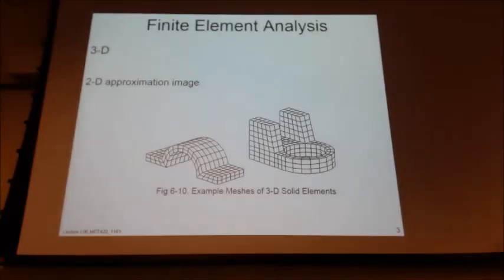And again, like in 2D, the tetrahedron wasn't used very often. We don't use it very often in 3D either. It gets used occasionally for transitions or tight radii maybe. But for the most part, we end up using hexahedrons.